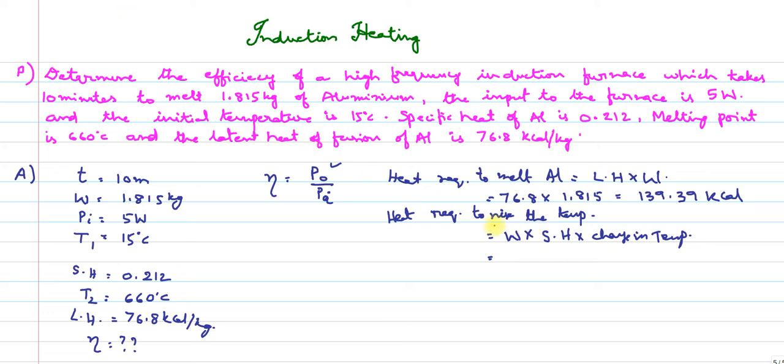It is 1.815, into the specific heat 0.212, into the change in temperature, 660 minus 15. So this will come around 248.18 kilocalorie.